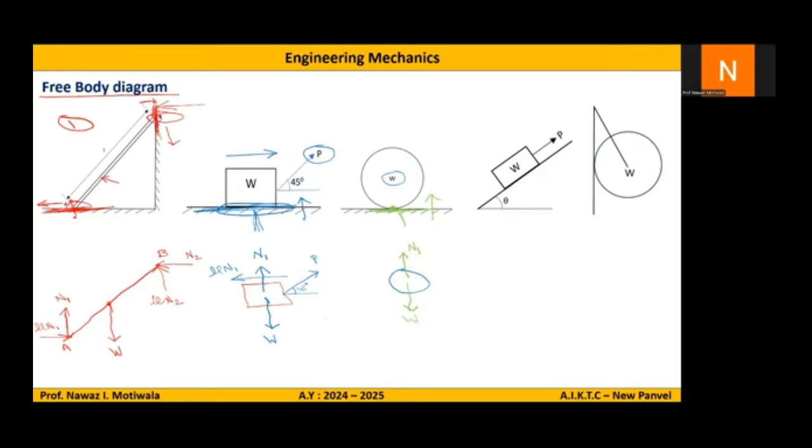Now the last force. The last force is the frictional force, which is in the direction opposite to the motion of the body. Now let us assume, as the direction of the motion is not given, that this is moving in the clockwise direction. So when this circle or the disc is moving in clockwise direction, this particular point which is in contact will move towards this side.